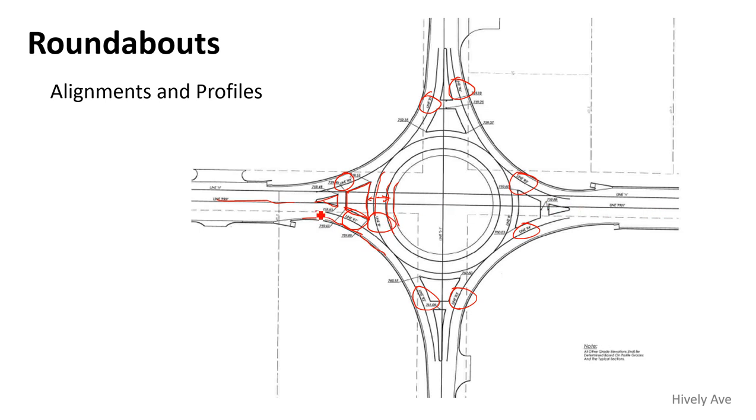And then these start here, and they've got an offset point on tangent off of that center alignment line. They pick up, it's probably 2% straight over. They pick up the elevation off of that line, and then they run with it. And they go through here, and then they match into that. So this is a whole lot of alignments. They all have to match up perfectly where they meet, like right here, right? And so in each quadrant, you've got a spot where all those lines come together. It could be for a little bit of distance, it runs as a single alignment, which is just that circulatory roadway, and then they pull off again, right, through there.